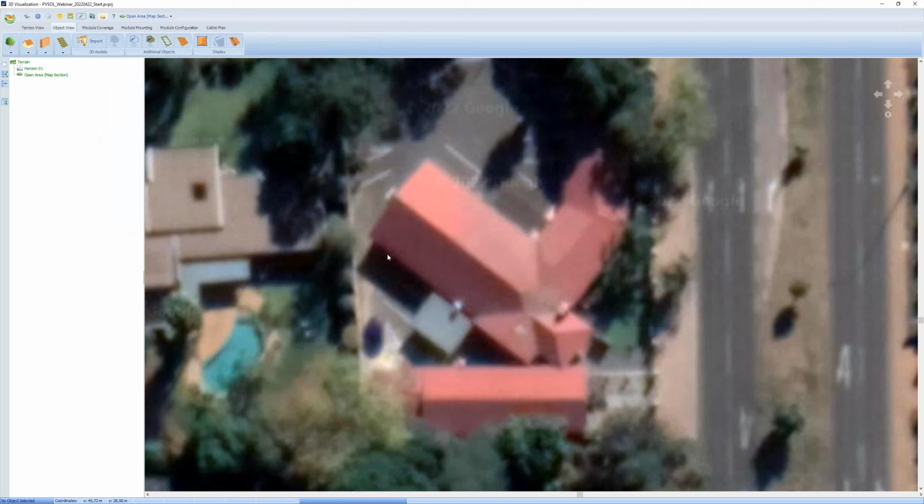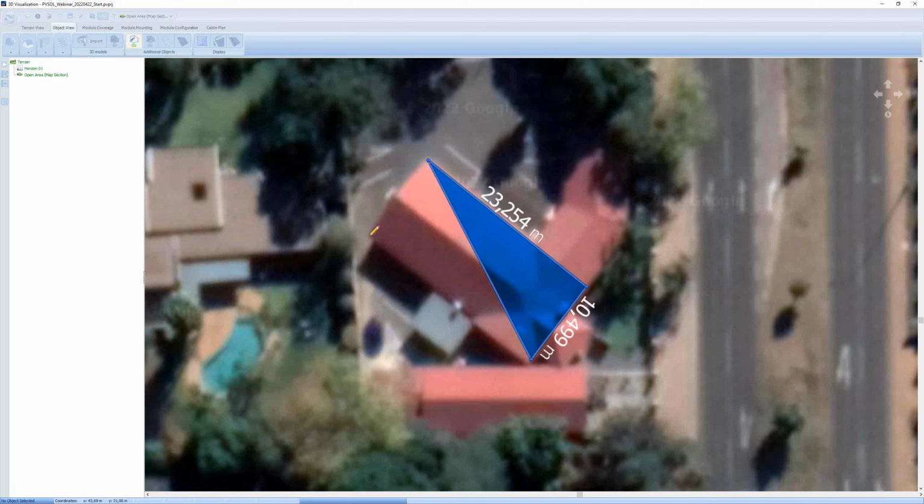As Sixten has mentioned, we will start with this one here. It's a building with a hipped roof, and therefore we are using the polygon tool. This means we have to sketch the outline of the building as well as the ridge. Then you can extrude the building, give it a height, and let's start. Just click a corner here. Also here. Then you have to press the enter button, and you can define the ridge of the building.